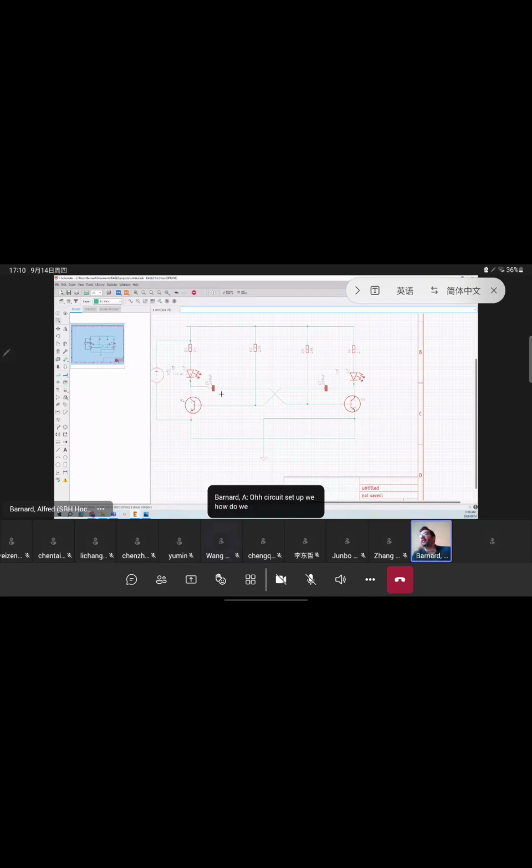How do we know when these diodes are switched on? Well, we can add in ammeters, or we can simply have two voltage probes, checking if voltage is flowing through these elements. Right. And then let's start our simulation. Operating point does not really work. Let's go for transient. Let's take it up to around about 5 seconds.